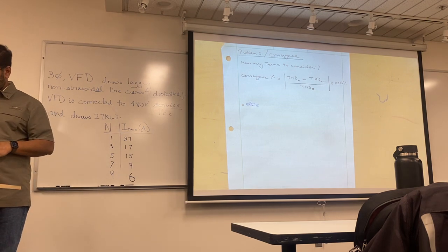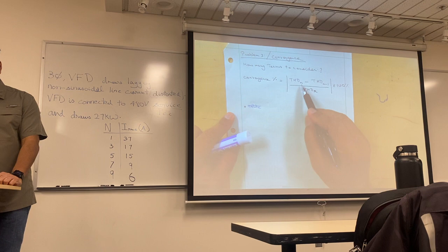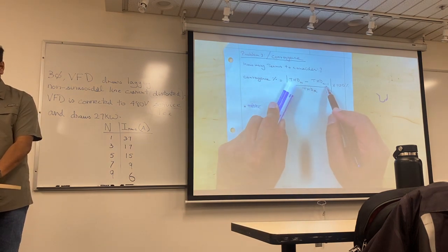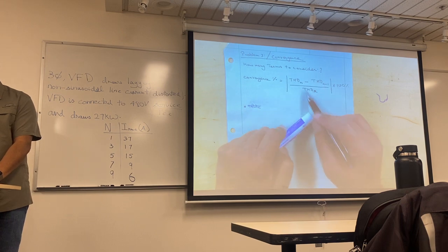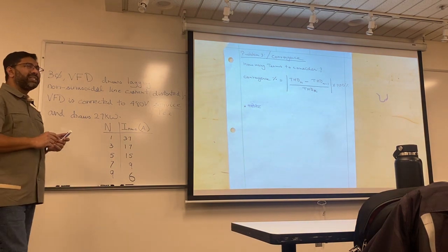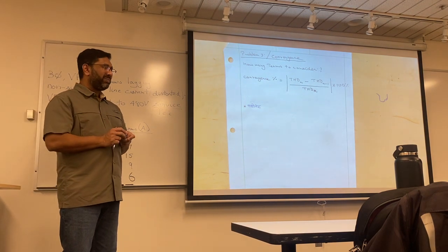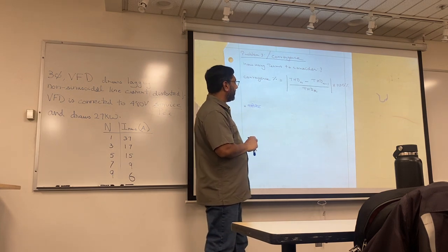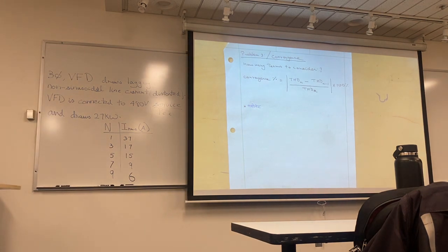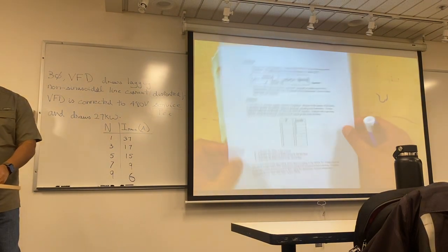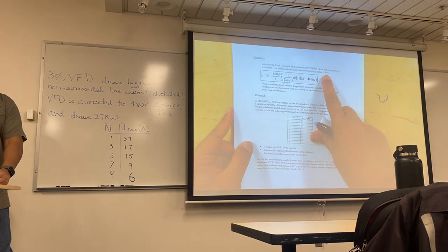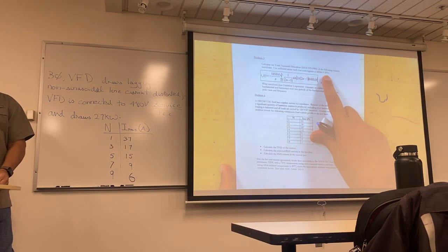So what you do is you pick a particular harmonic, let's say harmonic number 21, and then you do an n minus 1, so harmonic number 20, and you divide by harmonic number 21, you find the THD at n minus 1, and do this jazz and get a percentage. And typically we ask for 0.2, 0.1, that's good enough. Because after the 15th harmonic I showed you, the current just dropped, there's no point in keeping on doing stuff. But from a homework perspective, we asked you for 0.2.